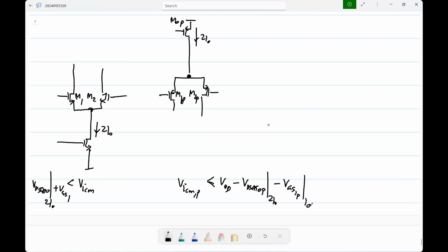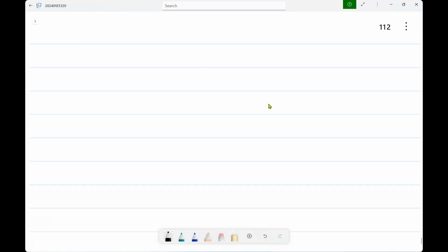Whereas on the other side, like the NMOS transistor, you can take the input common mode to a pretty high value. And in the PMOS differential pair, you can take the common mode to a pretty low value, close to 0 also, or maybe even below 0. Okay. So now sometimes this may be a requirement, especially if you have a non-inverting unity gain buffer like this.